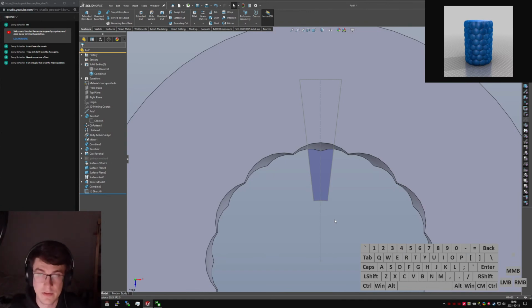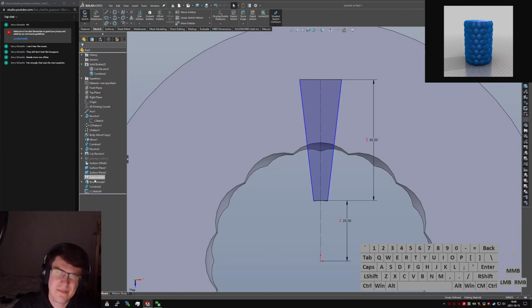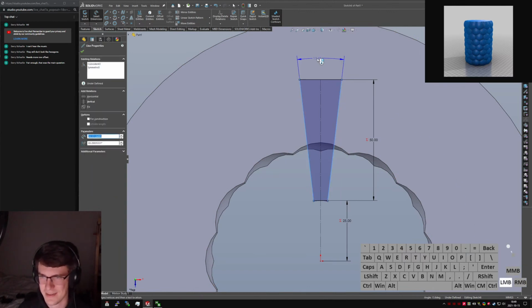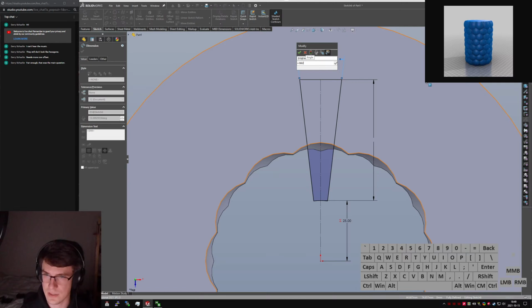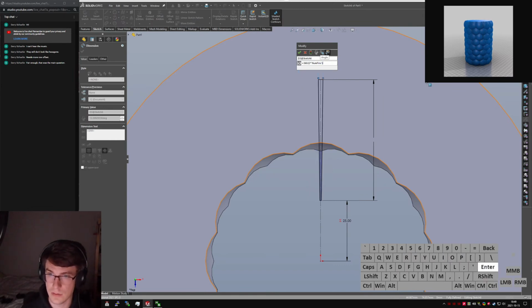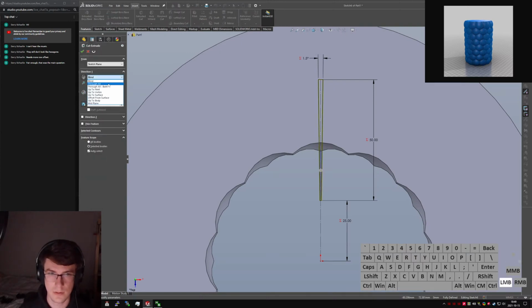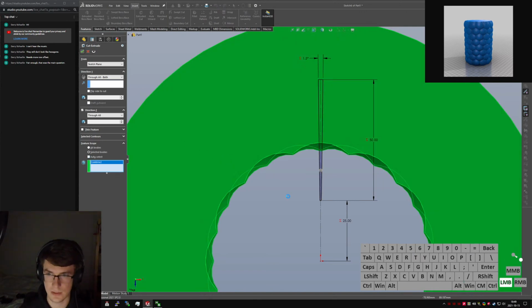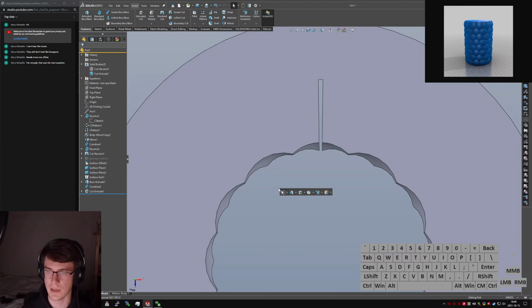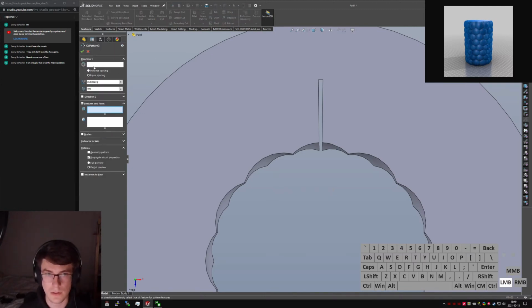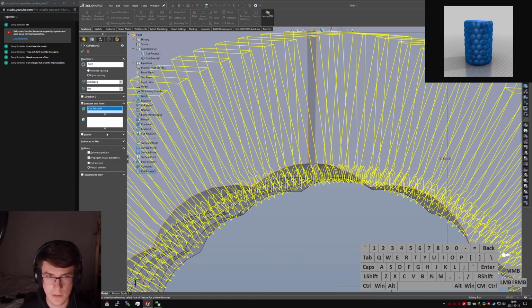I mean, if I was smart, I would be doing this all from the equations and then driving the sketches from the equations rather than computing things in the sketches, but... So we want this distance to be equal to 360 divided by 2 times num fins. We want that extruded cut through both directions. Don't auto-select, subtract only from this body. Then we do a circular pattern. Direction 1 around our axis. Features this one. And we make this equal to num fins.